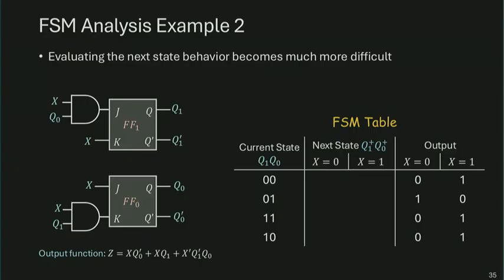Right. So how do we do it? We have two choices, simulation and Boolean algebra. With simulation, you can say, well, I plug in the value of, let's say, the first condition, 0, 0, 0. So these are all zeros. My flip-flop inputs are essentially 0, 0, 0, 0, which is a hold condition, which means my next state is 0, 0. Right, do that for 1, do that for 2, do that for all 8 combinations. You can fully recover the state table.